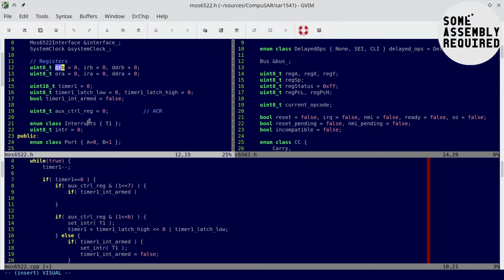One way is to actually change bit 7 in output register B. And the other way is to say pin PB7 is taken from output register B unless ACR bit 7 is set, in which case it's taken from a different register. And I don't know which of those the 6522 does. I will have to check it on an actual chip. So for now, I'll leave a comment.